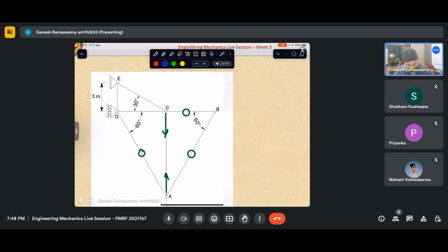If these two are collinear, then the third force in the member is 0. So this also becomes a zero force member. So essentially, by removing just one force from our system, we can see that so many member forces go to 0.